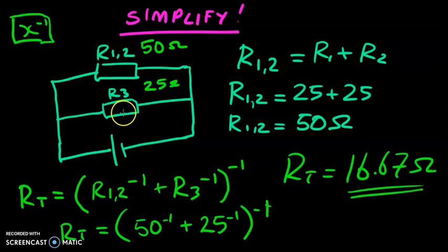So always simplify. If it's overall series, you solve the parallel parts first. If it's overall parallel, you solve the series parts first. That's really important. Okay.